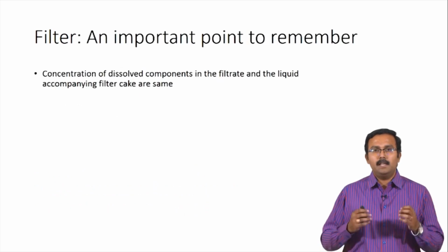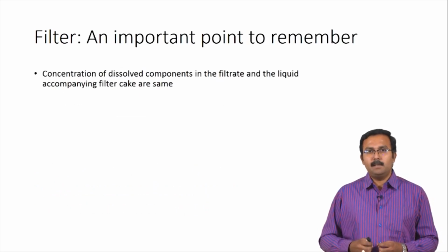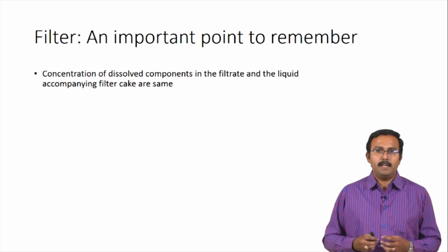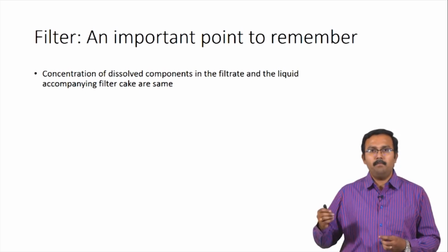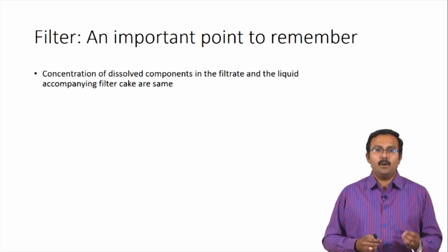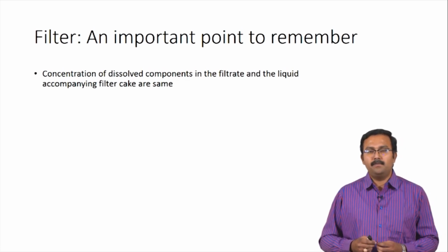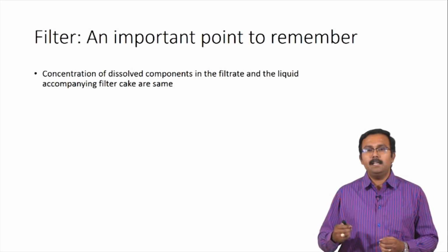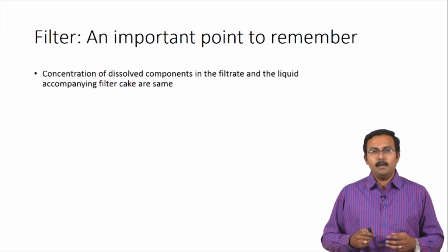So, now there is an important point which needs to be remembered when we talk about a filtration process, so that we can perform material balance calculations. It is that the concentration of dissolved components in the filtrate and the liquid accompanying the filter cake are the same. What do I mean by this?